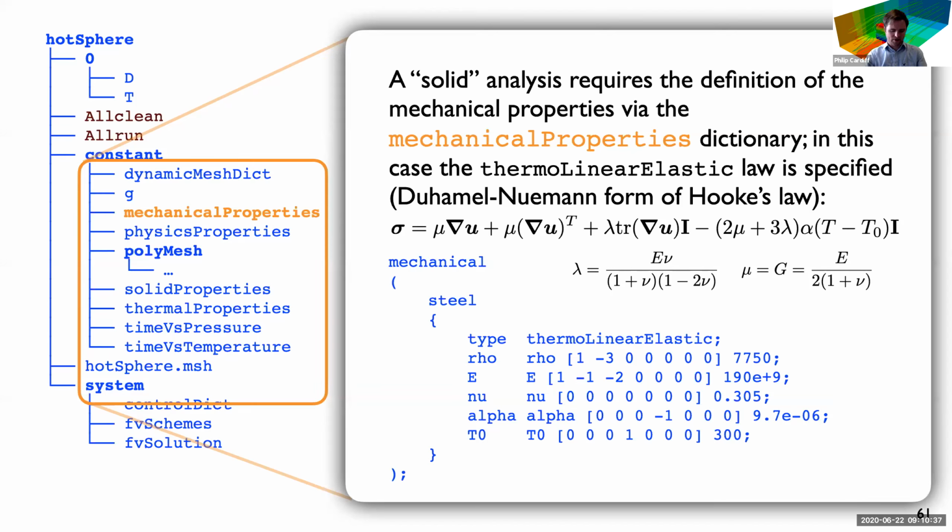So like a normal linear elastic material, you specify Young's modulus and Poisson's ratio. So Young's modulus is stiffness. Poisson's ratio is how much it contracts in the other directions. 0.5 would be incompressible, so generally we use a compressible approach. And these are your thermomechanical parameters, so coefficient of linear expansion and a reference temperature.